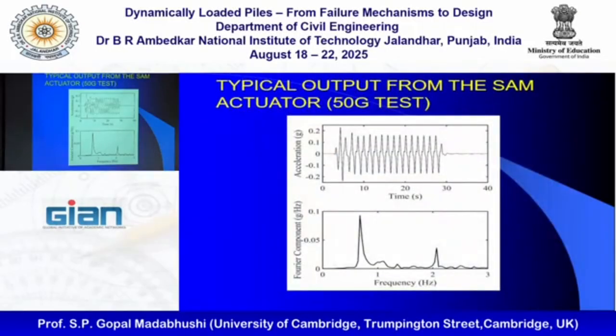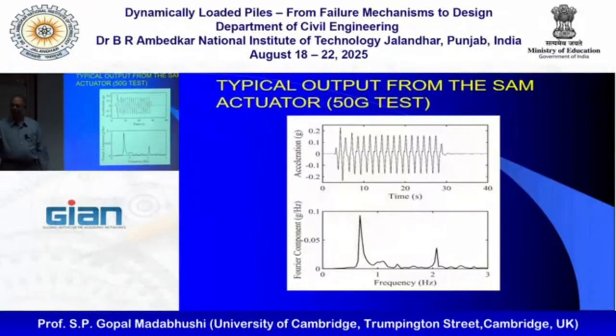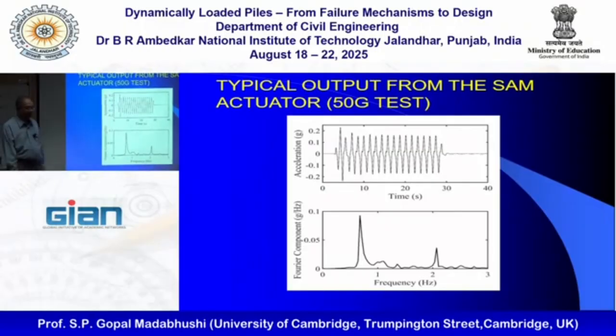So finally, here. This is very clean sine wave motion. It's a mechanical actuator. And if you do the fast Fourier transform of that, you can see it's produced at about 0.8 hertz prototype scale. It has concentrated energy. Sine waves have that nice feature that you can have all the energy at one frequency. And then once you apply this, you can see how your soil model and structure model are changing. What is the frequency response for that?